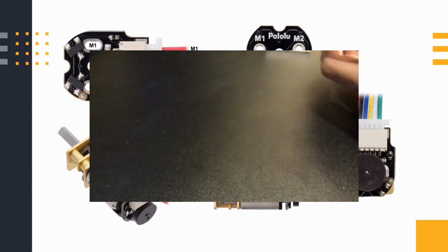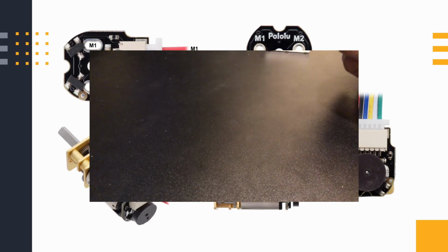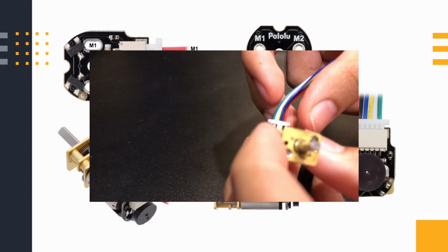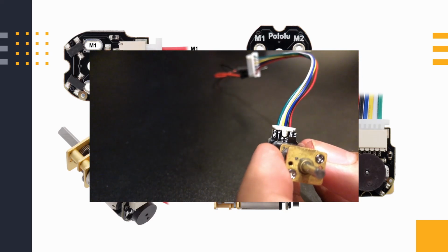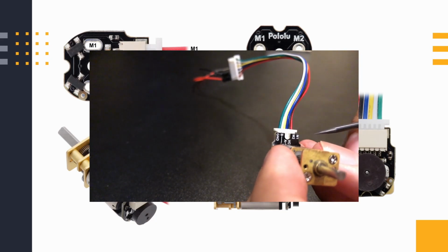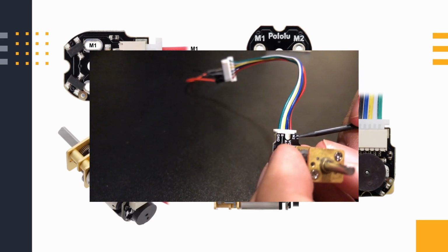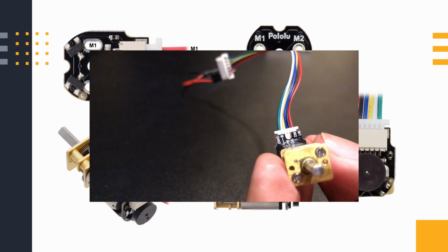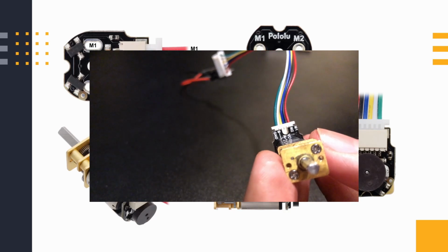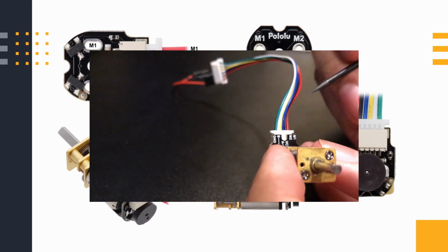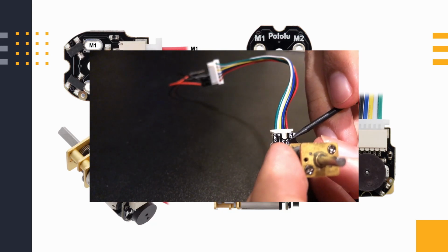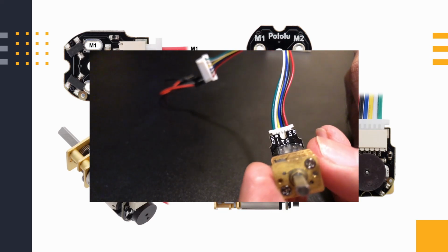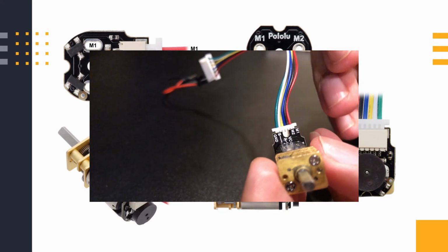And just to give a little demo of how this would work, if you can see the markings on these encoders, M1 and M2 correspond to the power that's going to be going to the motor. So M1 and M2 are going to be connected to these two holes right here, and then power is going to go through that into the motor. GND and VCC do not go to the motor. GND and VCC are actually power for the sensors themselves. So the power supply for the motor and the sensor are going to be separate.